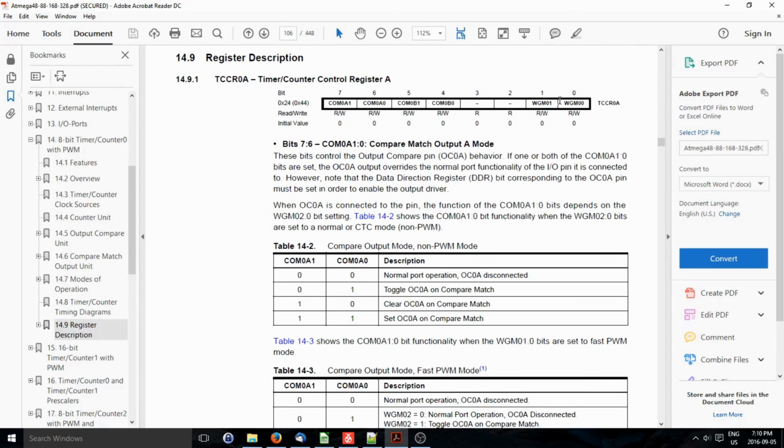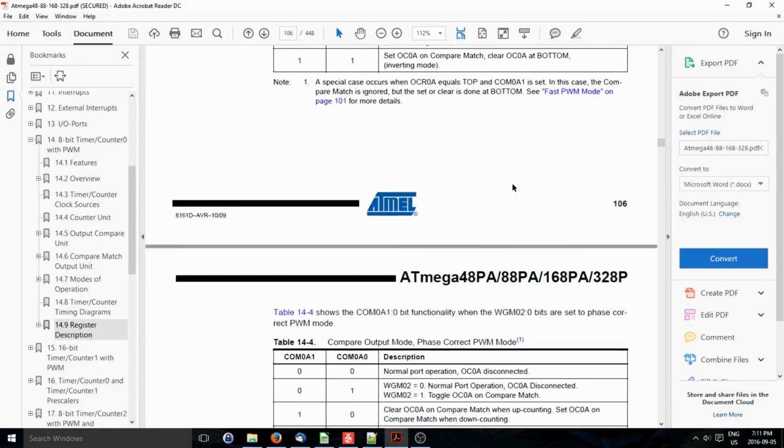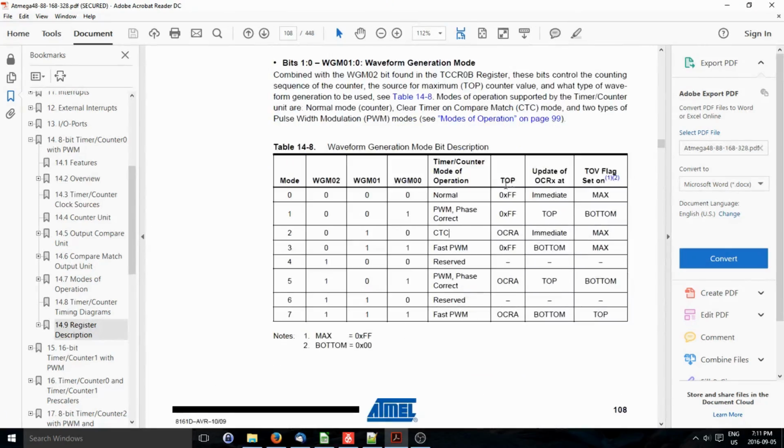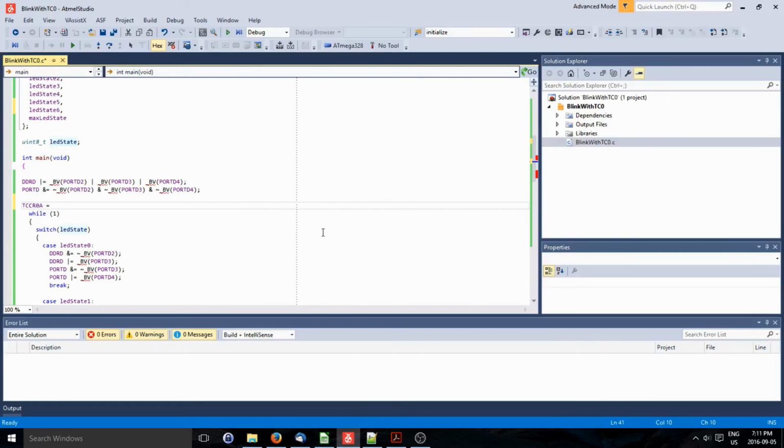Actually, oh yeah, we had reset values of those two as 0, 0, and we are in the mode, scroll down here. So it's 1, 0, so we have to write 1, 0 in the upper 2 bits, and then nothing else, everything else is 0. So we can just write to it directly. We don't have to do this bit manipulation like we did here.